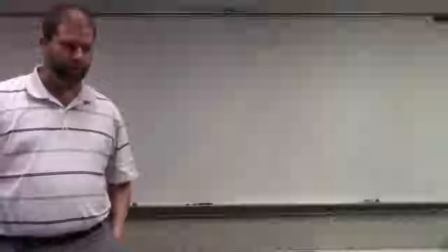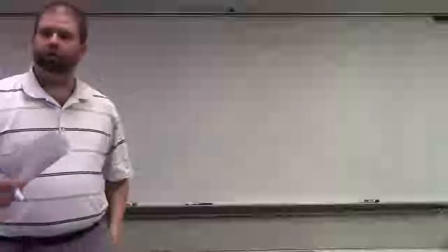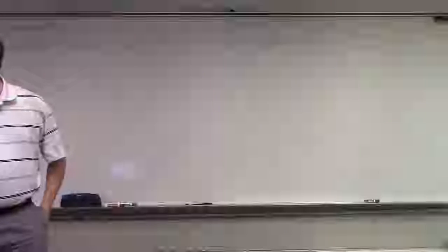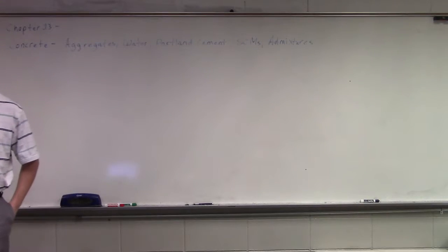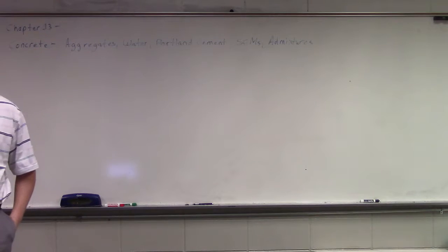So we should remind ourselves, and we've talked about it already this semester, but what type of axial force does concrete do well in? It does very well in compression, right? And it does poorly in tension. So the portion of this chapter that they're focusing on is how do we reinforce and why do we reinforce? The majority of the time is about tensile reinforcement, and that's all that we are really going to have time to focus on.